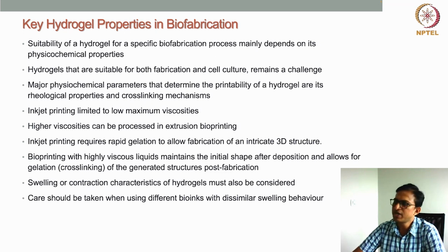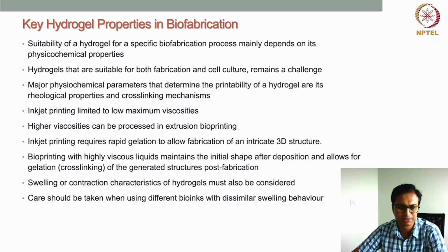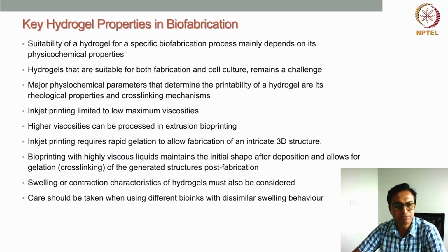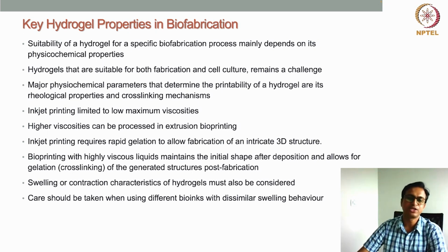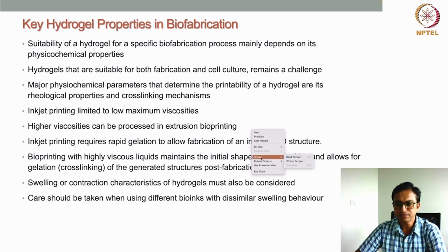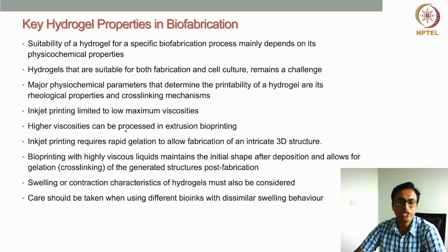But in extrusion based bioprinting, we may use higher viscous materials, which has some advantages. We'll see what the advantages are when you use high viscous, and what the disadvantages are when you use low viscous materials in bioprinting. So inkjet printing requires rapid gelation to allow fabrication of intricate 3D structures, because in this case the viscosity is very low. And when we use high viscous liquid materials for bioprinting,